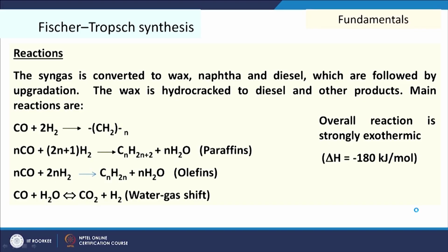One is Fischer-Tropsch synthesis. In Fischer-Tropsch synthesis, syngas is converted to liquid fuels, that is, diesel, petrol, kerosene, etc. So, what happens in this case? At first we get wax, then the wax is hydrotreated to get different products of it after fractionation.